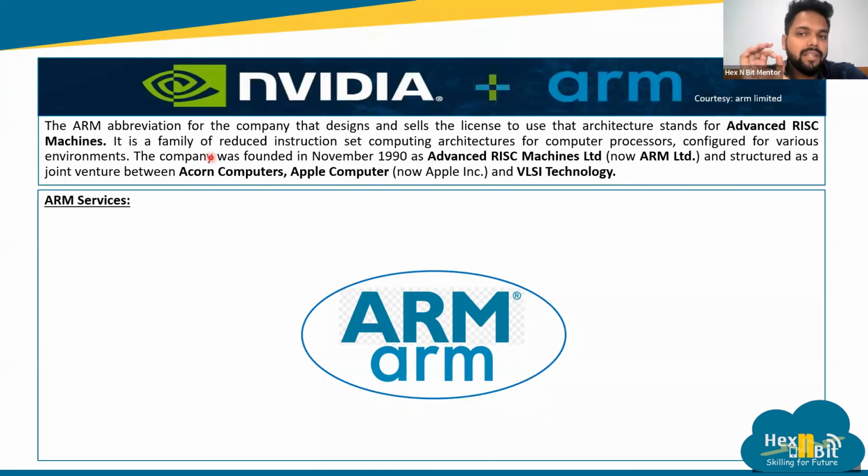First of all, whenever anybody asks what is ARM, what is a controller, you have to remember the differentiation between architecture and microcontrollers or microprocessors. ARM is an architecture, and semiconductor companies like ST take a license from ARM in order to integrate that architecture into their chipset.